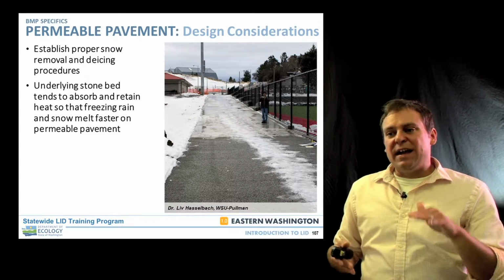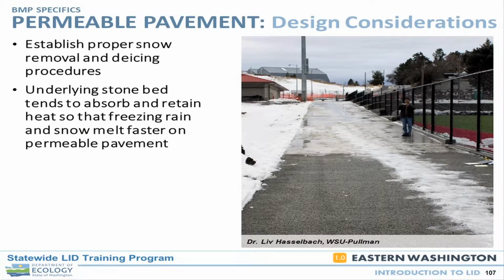But snow can kind of get compacted and ground into there, and you definitely don't want to sand your sites. So that's another consideration, is how often you're going to be plowing these sites. If it's not going to be plowed very often and it's going to still receive a traffic load, it may plug up during the winter because you're compacting that snow into that zone. So you don't need to do as much de-icing, but you may need to do pretty extensive plowing to make sure that you're not just grinding material into those pore spaces throughout the winter.